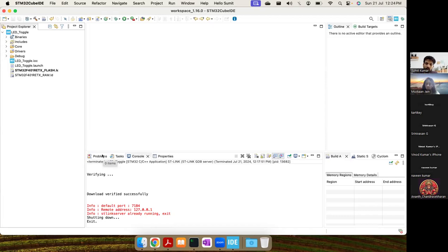Now, there are various modes like open drain mode and push pull mode. What do you mean by push pull? Push pull means there is a PMOS transistor and an NMOS transistor connected. In the output mode, there will be a pin, and the internal part where the signal goes to the inner part, telling the processor what to do. Push pull mode is a mode where we do not require any pull up resistor or pull down resistor. Normally we see push pull mode in the output mode, right?